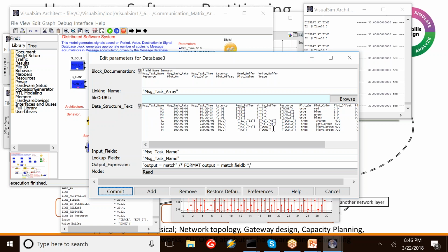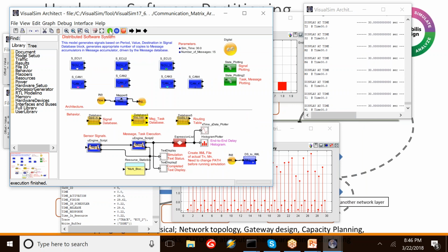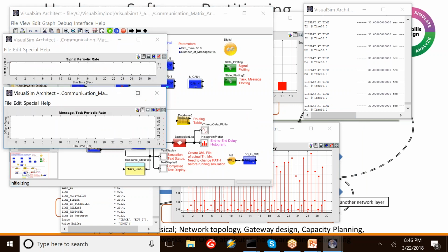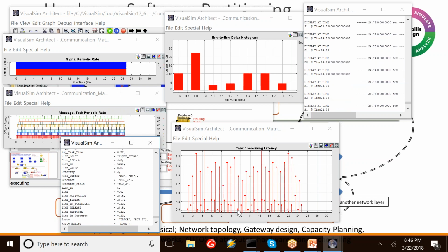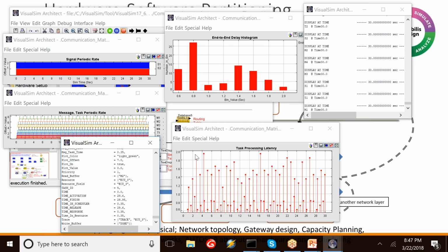Now what this does impact is that T2 is dependent on M1, for example, which means the traffic profile on the network will also change. So now I'm going to rerun the simulations to see what my latency is. One thing you're going to notice right away: the bottom is still 0.6, but the peak is going up to 2.0. Most of it is at 0.8, but the rest is evenly distributed, and there's a long tail that takes you all the way up to 2.0. So by doing these changes, by reallocating them, I can see how things get impacted.